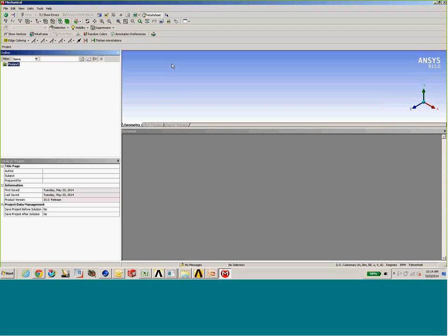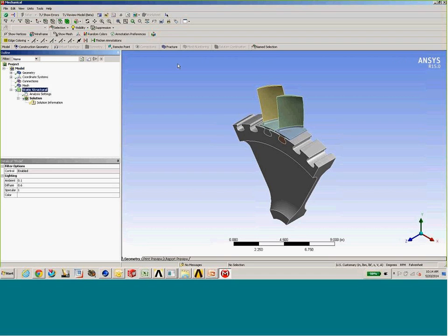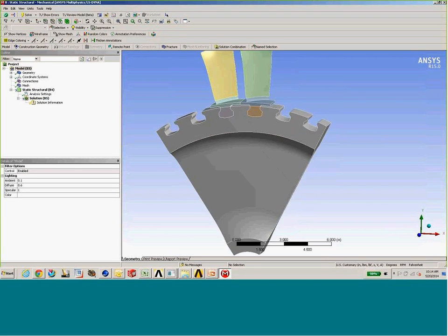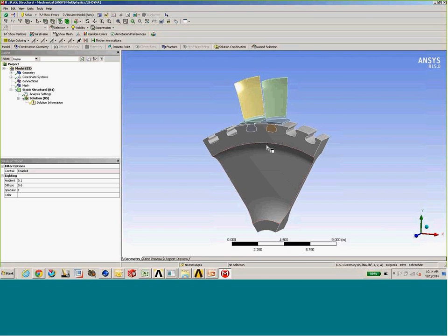And that's an important thing to keep in mind: when we bring a model into Ansys Mechanical inside Workbench, we have to have some geometry behind that mesh. Since we started with a static mesh in Mechanical APDL, something in that process had to create this geometry for us, and that is what's occurring right now with FE Modeler in the background. So we allow it to do its thing, and we'll notice that we get our part now in the mechanical environment.